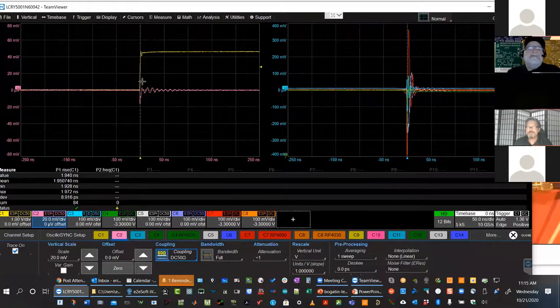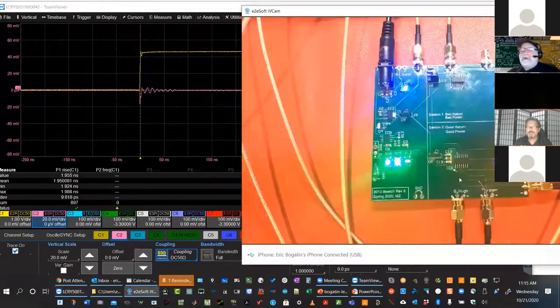This is the voltage noise on the board itself. This is some real ringing because of the size of the trace and the capacitance in the vicinity. But the voltage noise is 20 millivolts, not much at all. Let's take a look at the quiet low on the device itself. Let's see, that's going to be in channel 3.